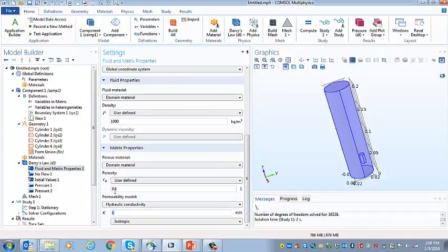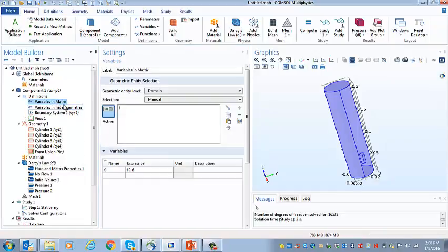So instead of having a number, we have a variable, and we specify the value of that variable up here under definitions. And in this case we have 2 pages of definitions that apply to 2 different subdomains, and they define the value of the variable for that particular subdomain. So that's another way of handling heterogeneities within this 3-dimensional model.